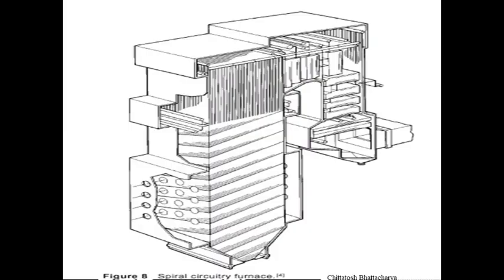In certain water wall systems, we can find spiral tubing. That means the tubings are not vertical, and particularly in supercritical boilers this spiral tubing arrangement is there, so that there is a high speed flow within the tubing with higher heat absorption rate.